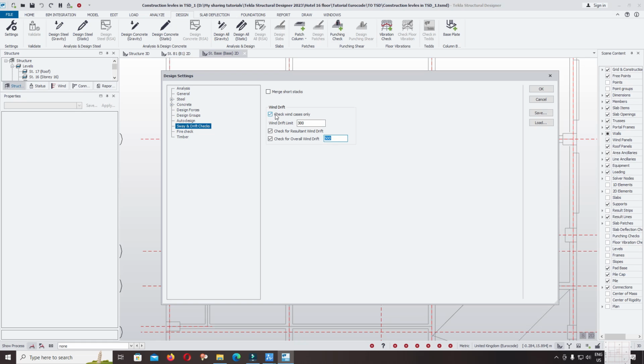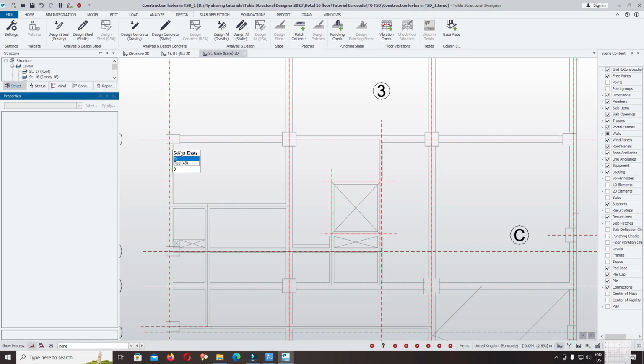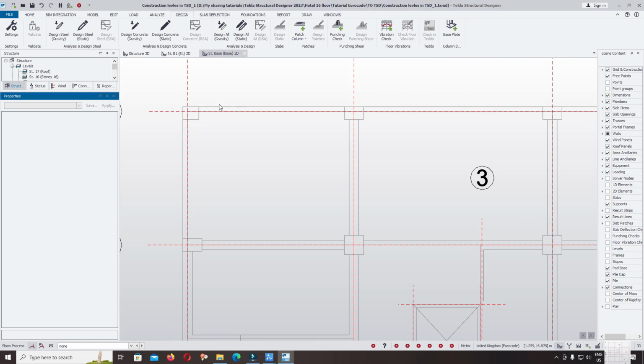For the wind 3 interstory 3 can rank from L over 250 to L over 300. In the default, the software keep the value is okay. It's acceptable. Okay, so now the column you want to change it differently from other column.